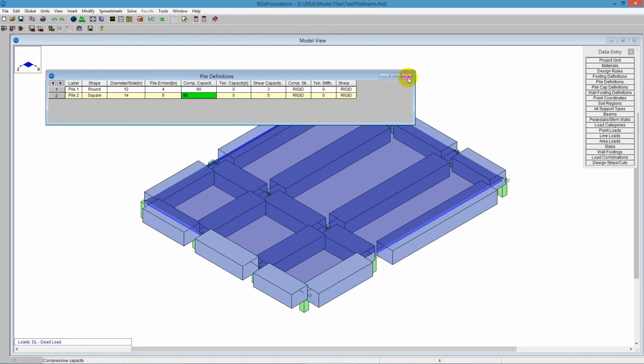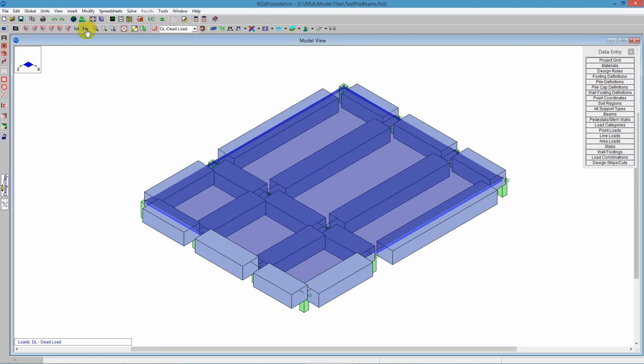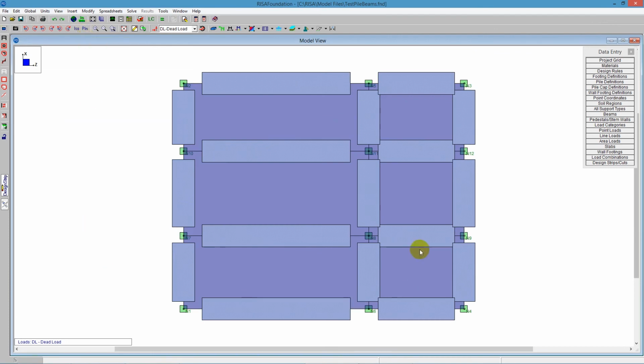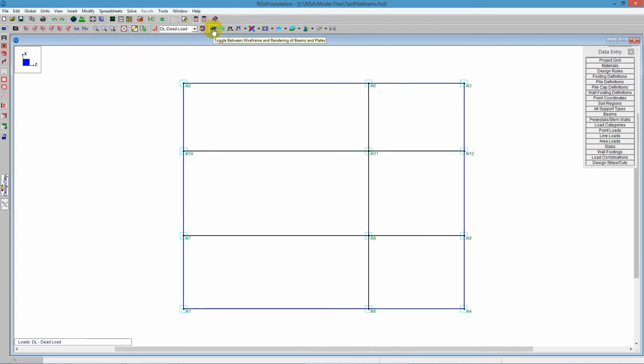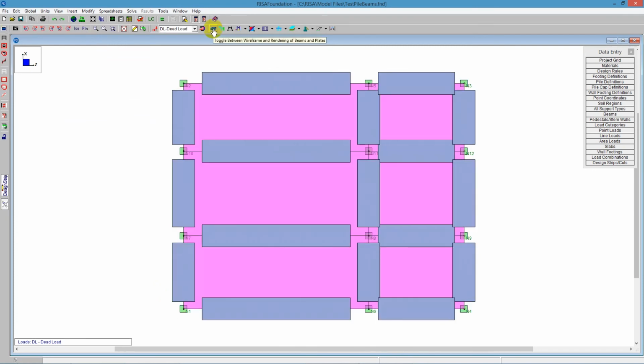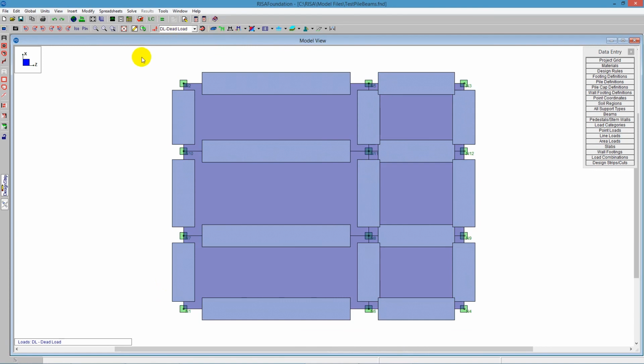Now, one thing to note when you're modeling a slab like this is that you are looking at the center line of these beams. So if the perimeter of the structure was out here on the edge, it would be important for you to model it so that you have offset that slightly, so you could actually have the perimeter of the structure be represented properly. So this is one method to design your structure, and if you did it this way, the piece we want to find here is that beam reinforcement.